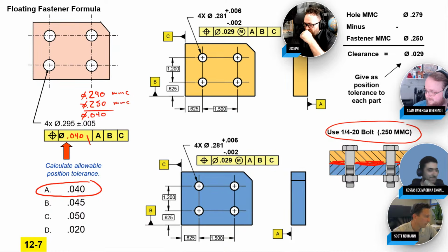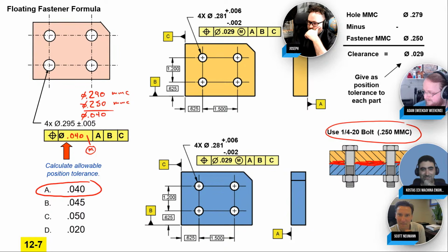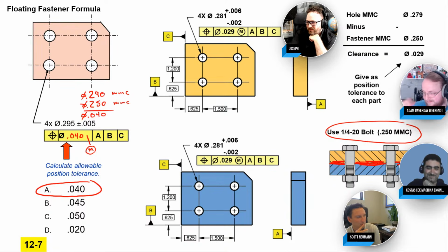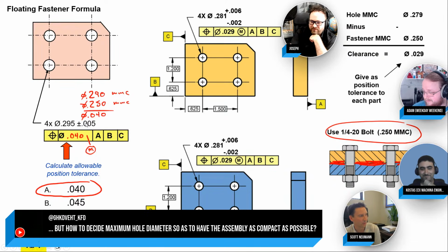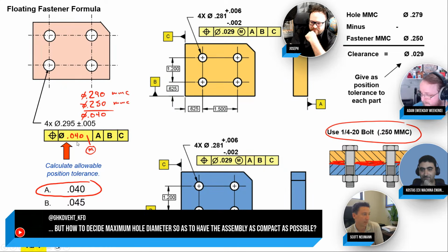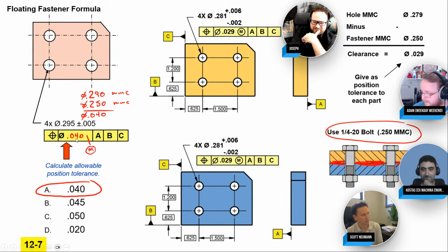Now, having worked on both sides, machinist and designer, machinists care about the tolerance as well because that's where the cost is, right? True. They're looking at the distance between your goalposts, and they're like, all right, I need to kick a field goal out here. What is the width on my zone? Good analogy. Here's that range between the goalpost, from a 290 to a 300. That's what they got to put that size of a hole in there. And then they also have another spec, make sure you're accurate. This is pretty loose tolerance here, 40 thou, but maybe for a shim or something that might be necessary.